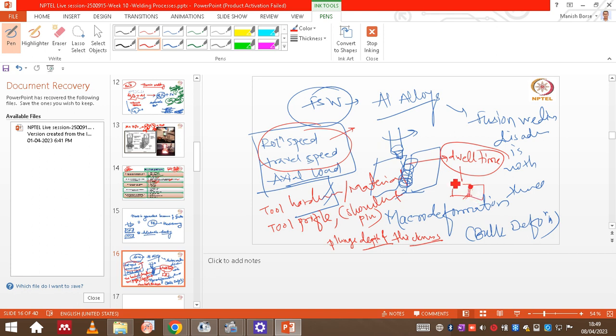Okay, because here we are softening the material, which means if we are increasing the temperature at the interfaces, sigma y will be decreasing, right? Why is sigma y decreasing? Because at a higher temperature, multiple slip systems are actuated. Okay, that means the material will flow easily, there won't be any restrictions, and that's why the material will plasticize or deform easily.